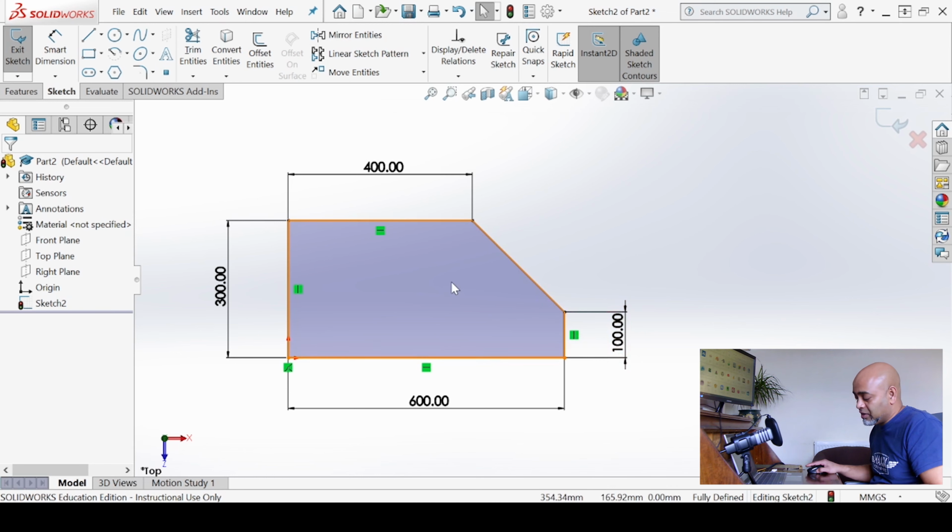Imagine if this was a piece of metal and you wanted someone to actually manufacture this for you. You'd say, start with a rectangular piece which is 300 by 600 and measure 100 from this corner here. That gives you a point. Measure 400 from this point. That gives you another point, and run it on a bandsaw or something and cut those 2 points out, and that gets rid of that corner there, and that gives you this net shape you're after. And hence it is fully defined this particular way.